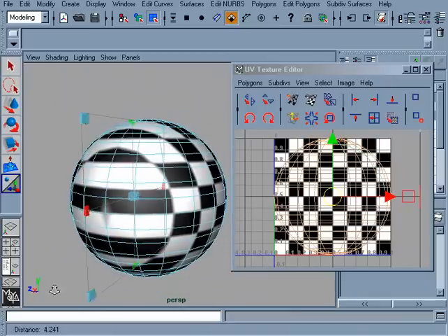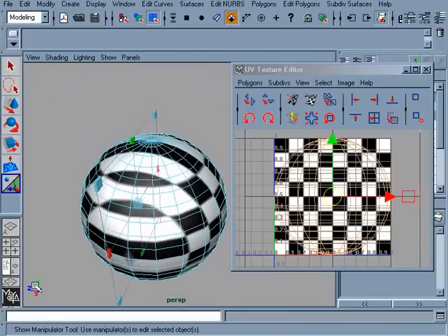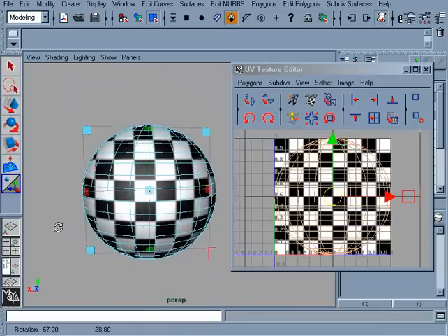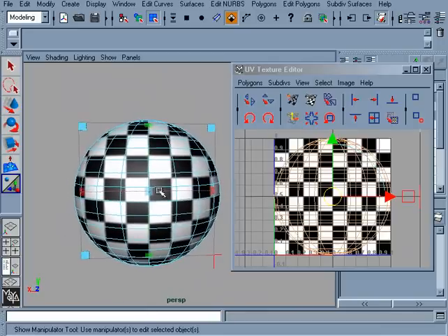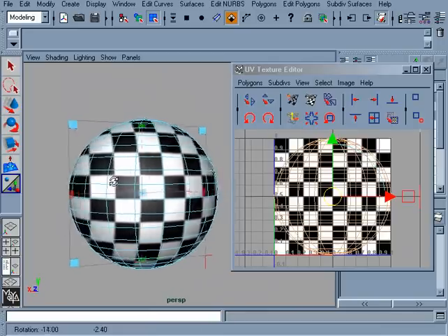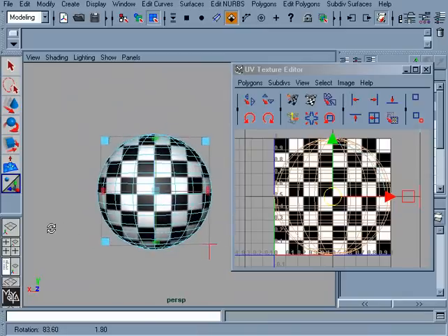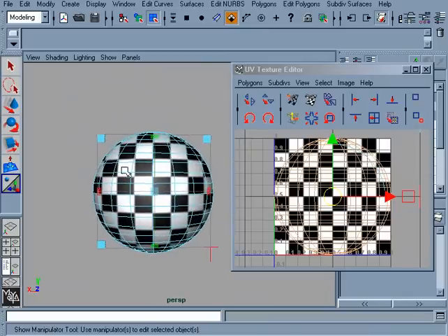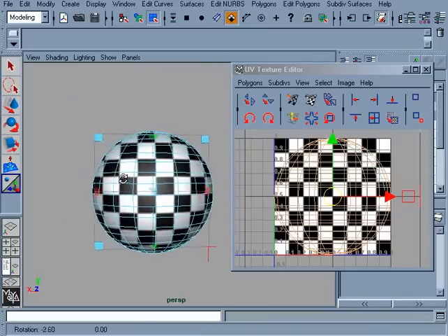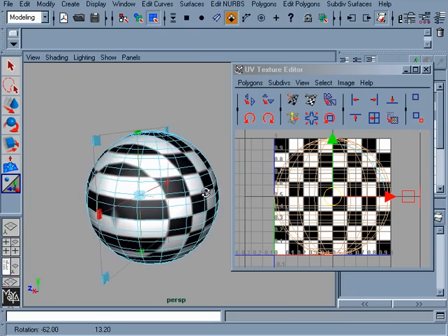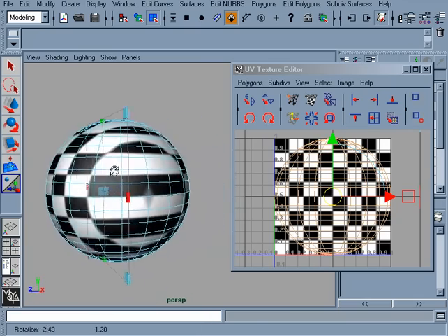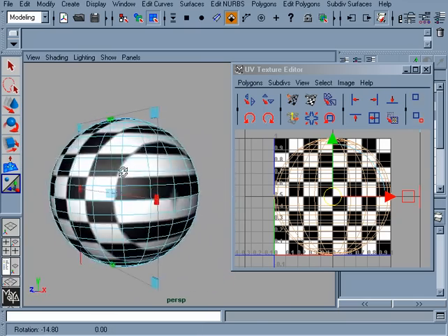If you look at your axis manipulators down in the lower corner, you can see that it projected it along the Z axis. Okay, so everything looks great in the Z-axis, but once you go to orbit around, you can see this area right here, and this is being caused by stretching in the texture. So what you have is a perfectly straight texture from this Z-axis, and the further around this object you get, the more that stretches until you come back around to the Z-axis again.